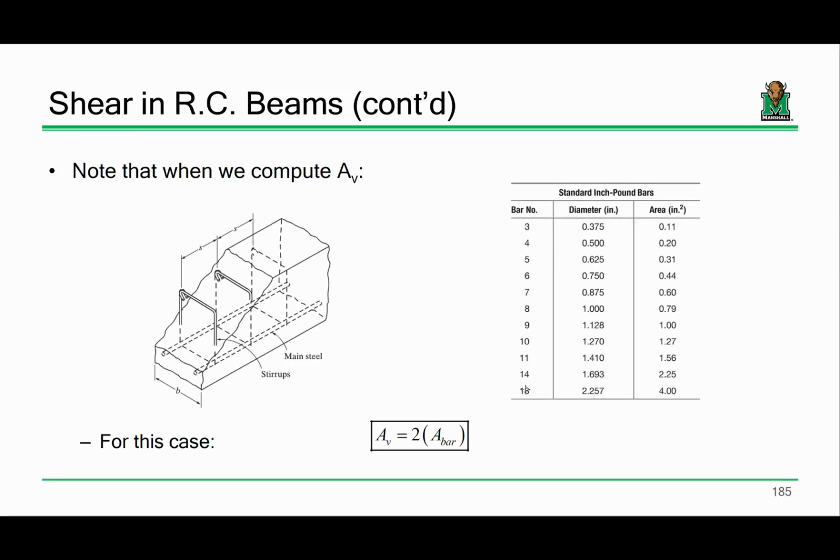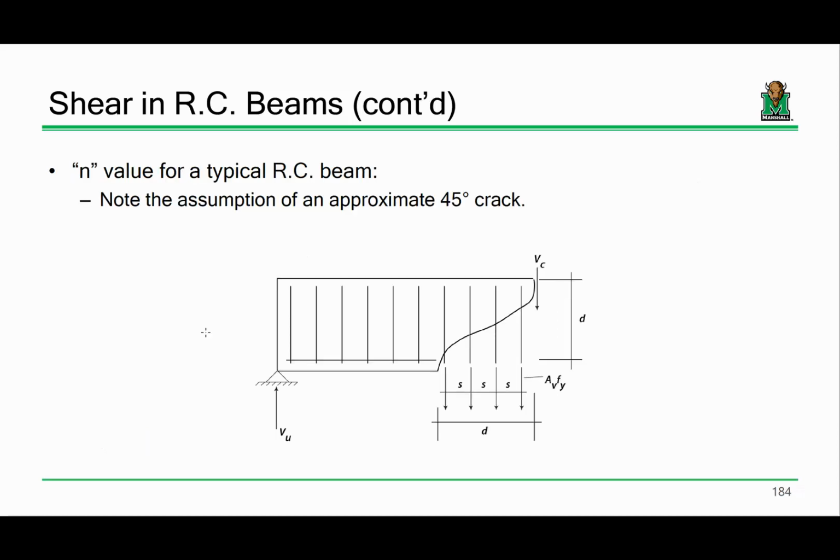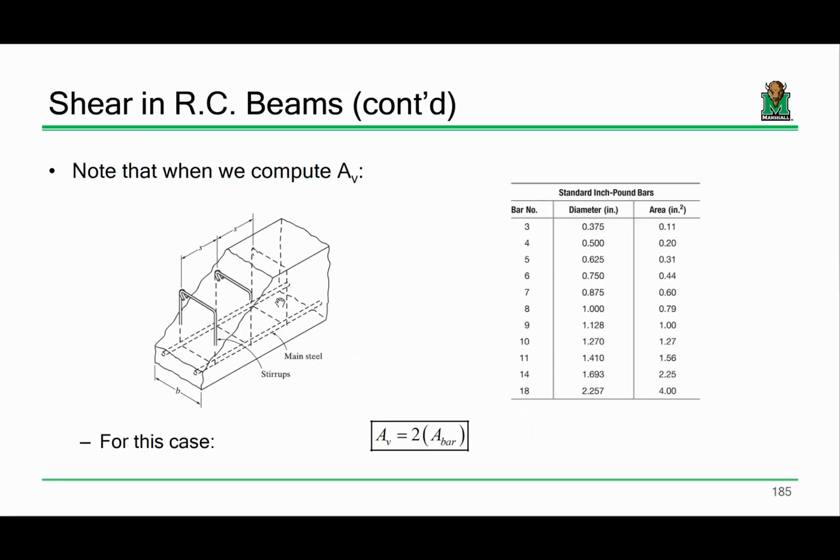Now, the other thing that you have to be aware of is when you compute A sub v. This image here on the left is a really nice example of that. Looking at this from a force standpoint, the force inside each one of these stirrups is the area times Fy. But you have to be very careful when you're computing the area. If you look at this three-dimensionally, let's say this stirrup is a number 3 bar.